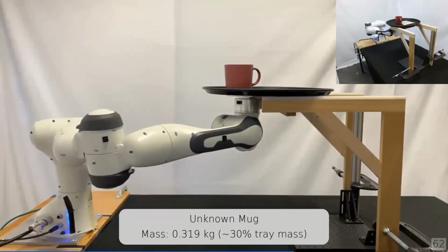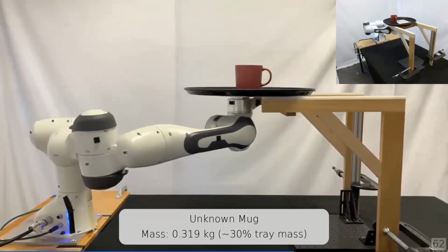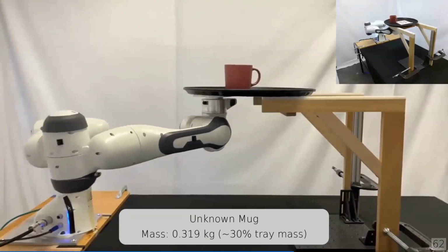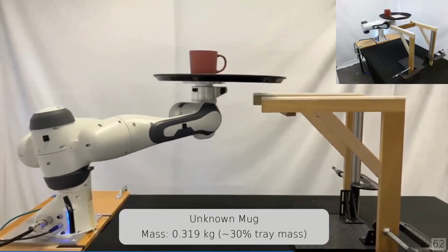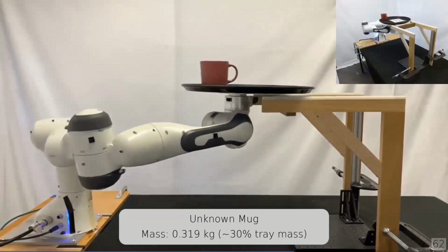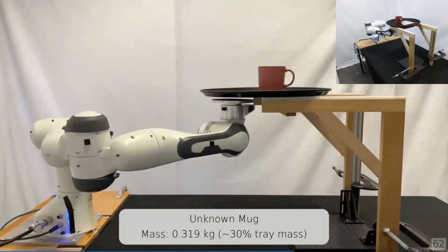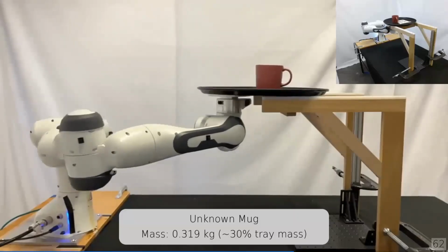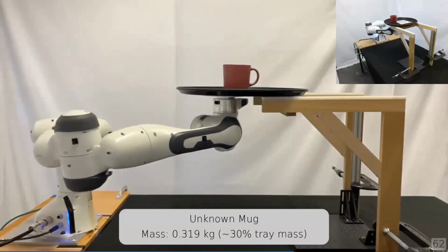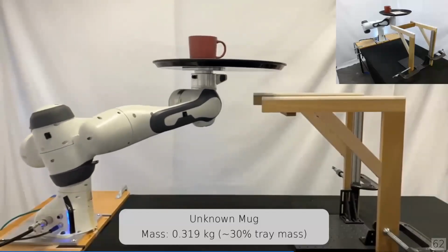One video I probably should have put in this talk shows that we can update the model when we stack two trays on top of each other. We have an April tag, not including the April tags, and we update the model in our system to include the additional thickness, the doubling in weight, as well as the change in inertia, and we can handle it really well. Actually, when you have two trays, it doesn't work anymore because it's too much of a disturbance, but if you update the model, it works. That's if the objects don't move relative to each other.